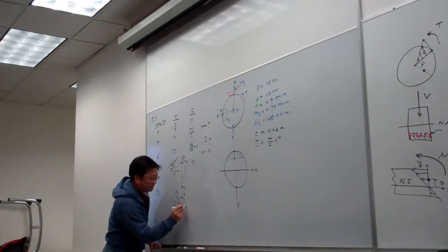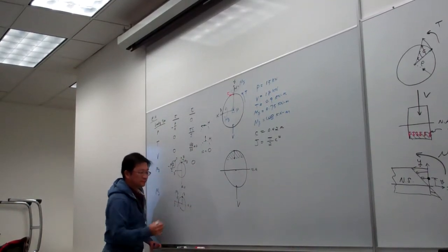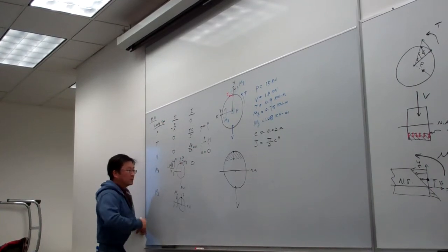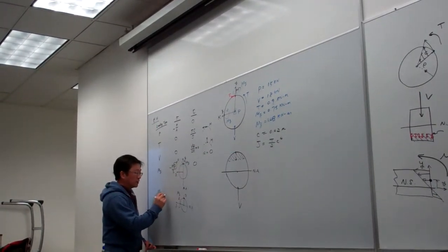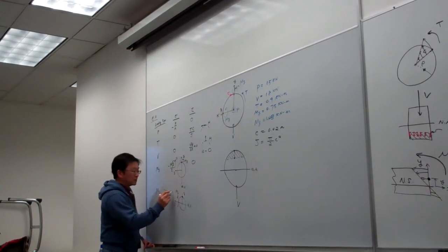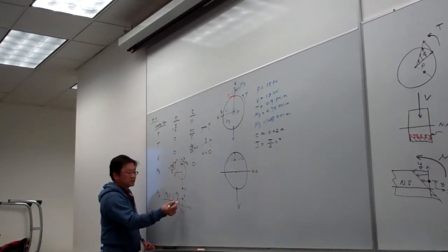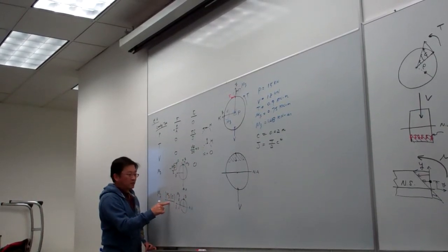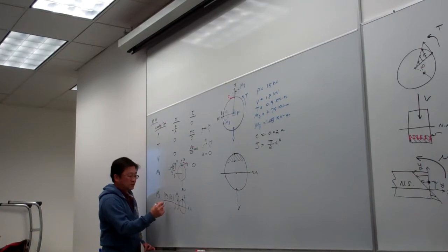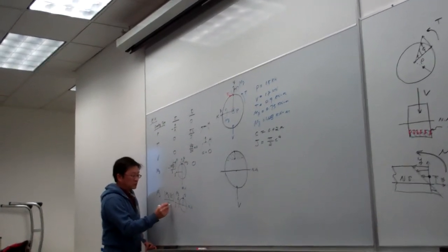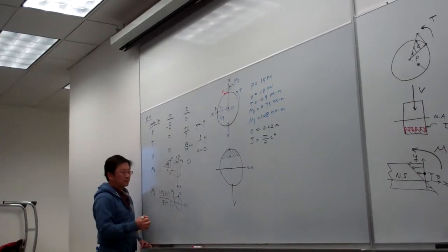This one is the neutral axis. Okay. So for this case, again we put into this formula the magnitude M, and the distance from the point to here, right? So that is c. And I is the moment of inertia with respect to the z-axis, which is pi over 4 c to the fourth power, right?